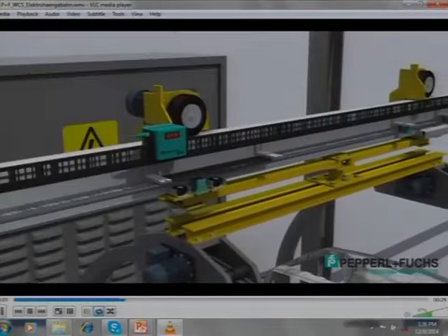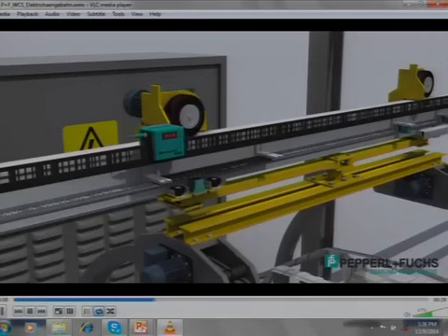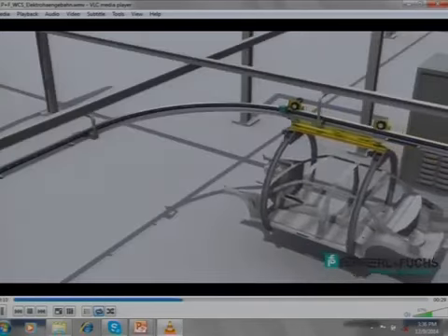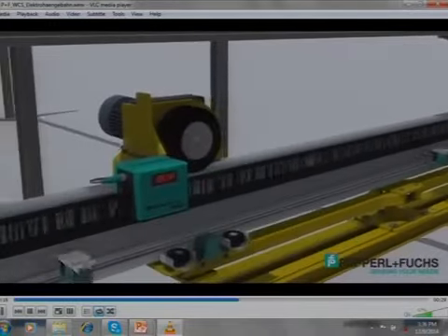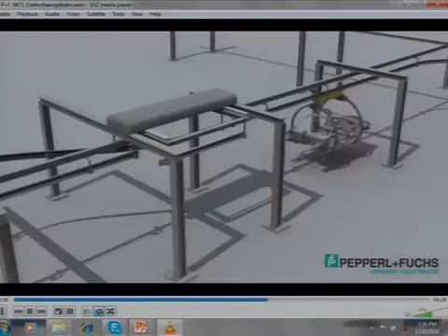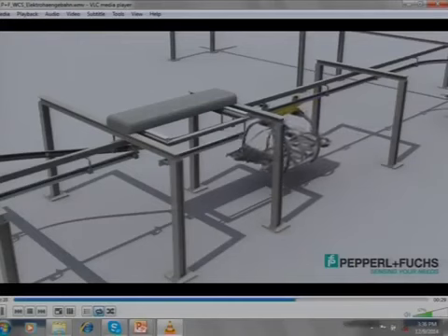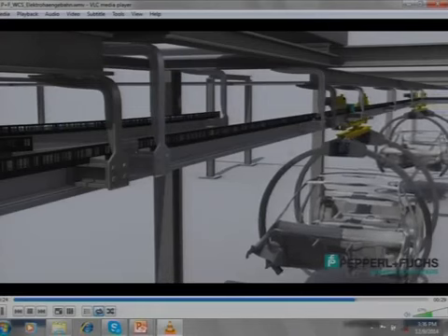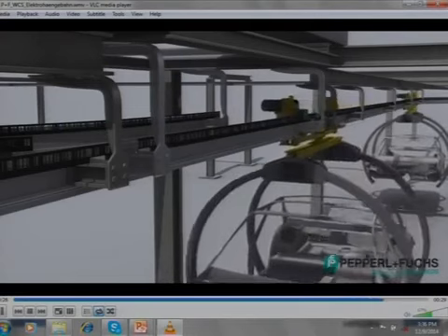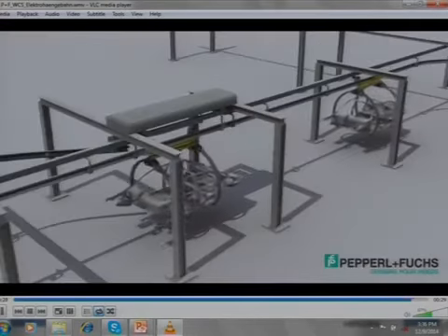Because in this case, whatever might be the case, the rail is not going to get destroyed. If you have a mechanical issue, you can take an SS rail. But if you have a chemical issue, you can have a polymer rail which is also coated so that any amount of vapor, you still get the same positions.